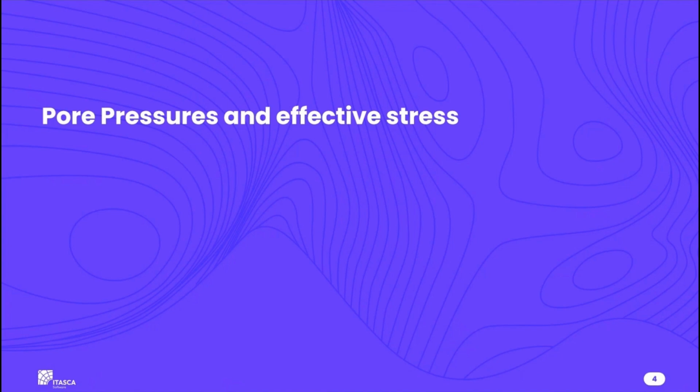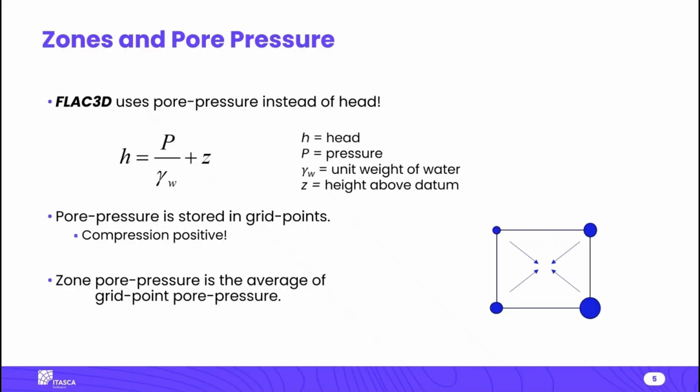So pore pressure and effective stress. If you've been following along this course from the beginning, everything up until now has basically been just mechanical calculations. It is possible, of course, to consider pore pressure in these models. The real reason of considering pore pressure, of course, is that it affects the mechanics, because usually you're looking at stability or deformation or something like that. So a couple of things to note about using pore pressures in FLAC3D or FLAC2D.